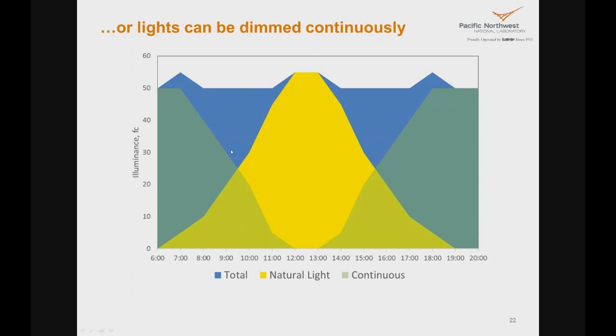This also helps with occupants because in the step system the lights can go on and off and there can be drastic changes in the light level, which can be disturbing and uncomfortable sometimes, and some people may complain about it. Whereas in this system, the change in the light level is much more gradual, and so this may be preferred by occupants.